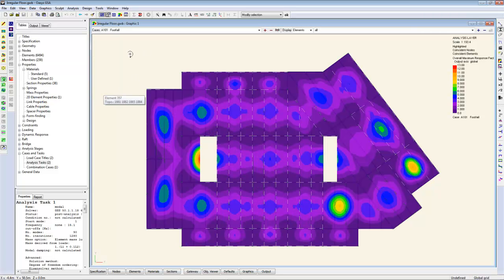Okay, you can see that in the regular bays, the footfall is moderate, 5 to 6 or so, but we're getting much higher values, 8, 9, 10, 11, 12 in some of the other areas, particularly next to this void. These would be areas where the simple method just could not touch.